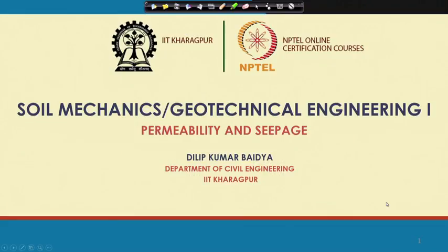So, various aspects of permeability we have discussed: how to determine the coefficient of permeability for different cases, how to determine equivalent permeability, how to determine it in the field and in the laboratory.